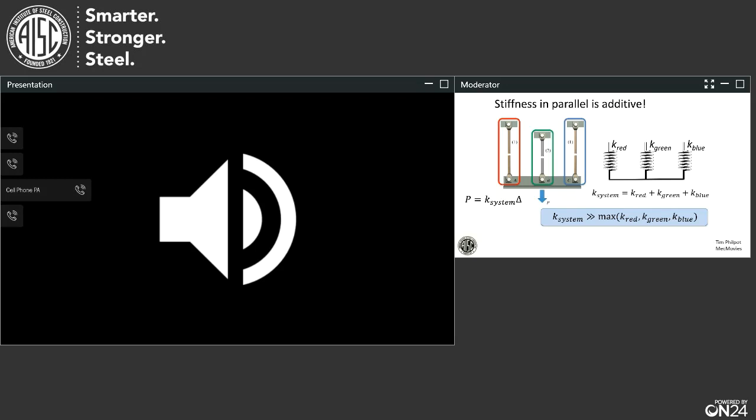Now, if the struts in between the two frames are not adequate, are very, very soft, no load may be getting into the other frame. But in general, if you have two frames side by side, each one should be doing their share based on their own stiffness in resisting the load. But yeah, good question.